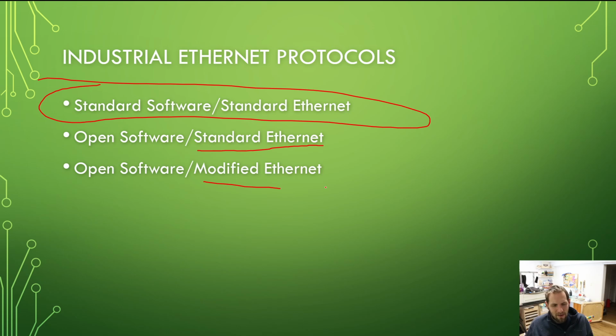And this is where EtherCAT, Sercos 3, and Profinet all use this architecture. But they do so with different hardware and transport mechanisms. So again, you can't use them interoperably. It's like, you gotta be kidding me. For those who are curious, Profinet would be the Siemens-based one. I forget what EtherCAT and Sercos 3 are based off of, but there are just some different options out there.